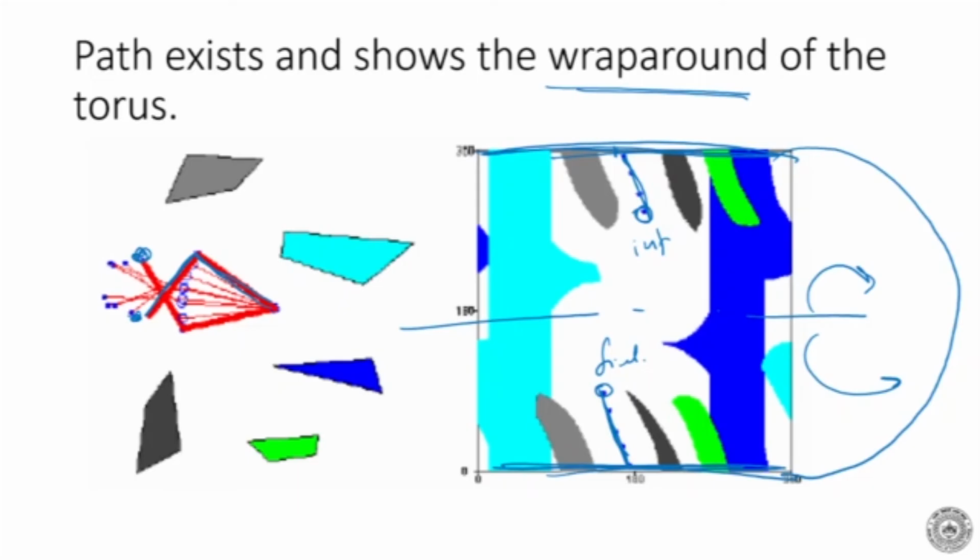We talked about ways of drawing the Cartesian space. So today's class we talked about how to draw the Cartesian space for a serial arm robot. And after you make the Cartesian space for the serial arm robot, if you have to find a path, it has to be path connected, which means that in the manifold there should not be breaks due to the obstacle, and the initial point and the final point should be connected in the manifold itself.